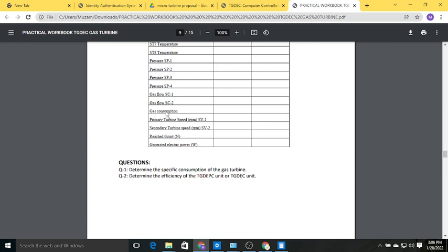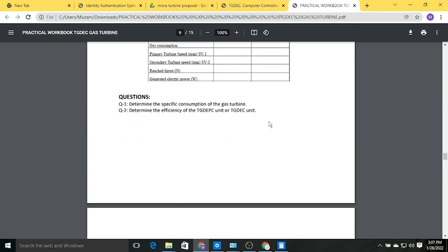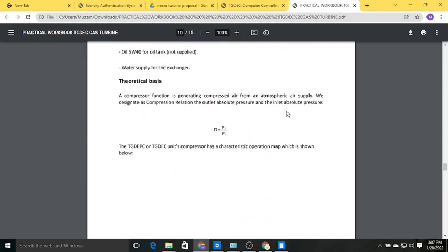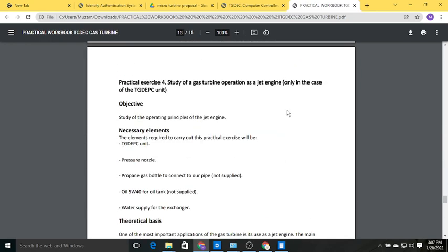Anyway, gas consumption is not calculated by SCADA. I tell you the manual reading is around 50 to 60, and I'll show the video too, which shows that it is running between 50 to 60 liter per minute. The flow is around this gas flow, propane LPG gas flow. Okay, so